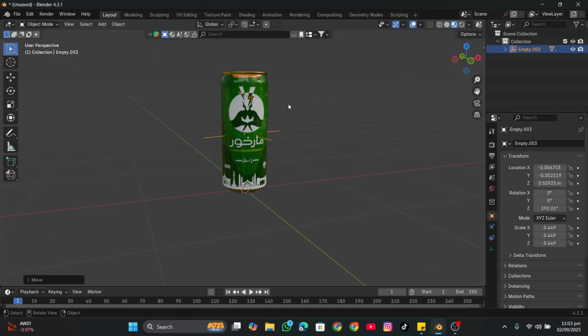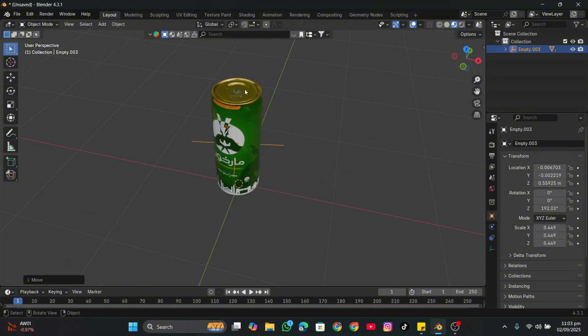Okay. So what we're gonna do is we need to first create the environment because it is important. Before you create the simulation, you need to have all the environment around it. And why is that? Well, it's because if you don't have the environment, then you don't have the collision object that the particle will collide with. So we need to make the environment first, and then we're going to talk about how to make the simulation, right?